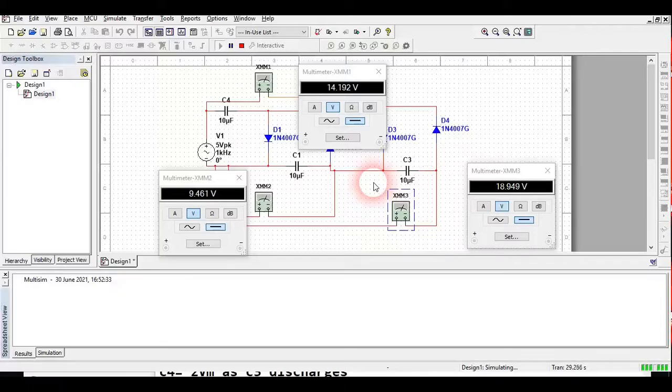Now a little bit of information here. One thing is that since diodes are here, we are getting some voltage drop. We will necessarily get some voltage drop here. Second thing is that these kinds of circuits we use when we need DC supply in a huge amount. We are giving here an AC source, remember this, and then we are getting the DC one. So this type of circuit also works as an AC to DC converter. You can see the output here, and you can analyze this.